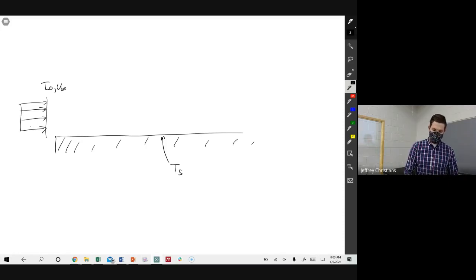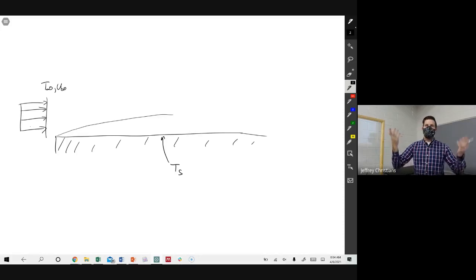So we're trying to understand this boundary layer growth. We have two boundary layers growing simultaneously. One is a velocity boundary layer, which we can think of as a function of the no slip condition, the fact that at the wall things are stopped. So that propagates up into the fluid. We start to feel it more and more as we go down the surface as time goes on. And the other one is the temperature boundary layer, driven by heat transfer, conduction really, through that first layer of fluid.